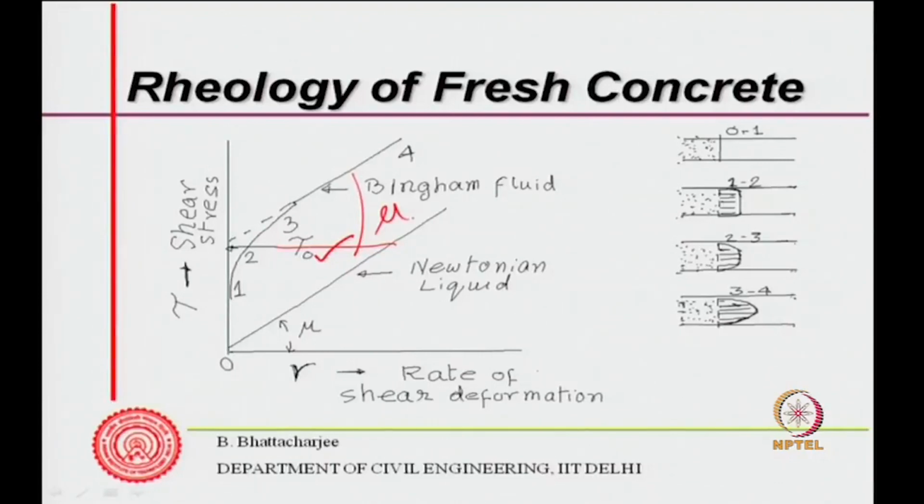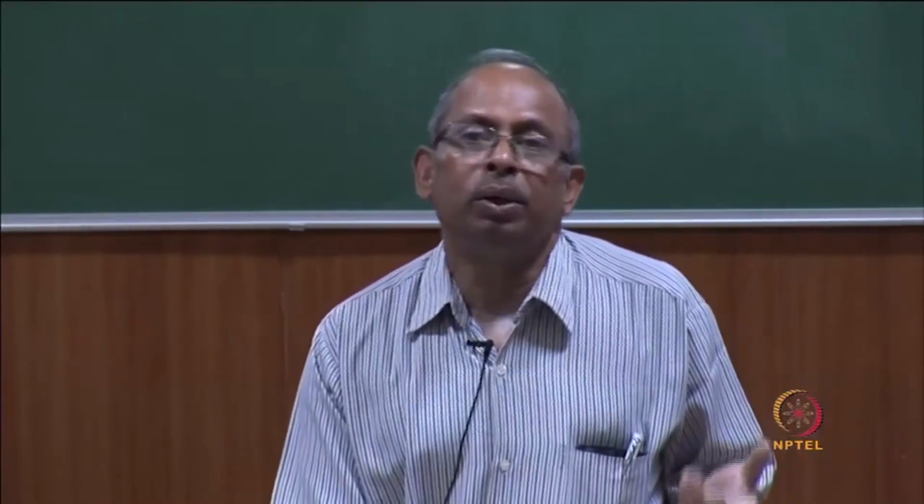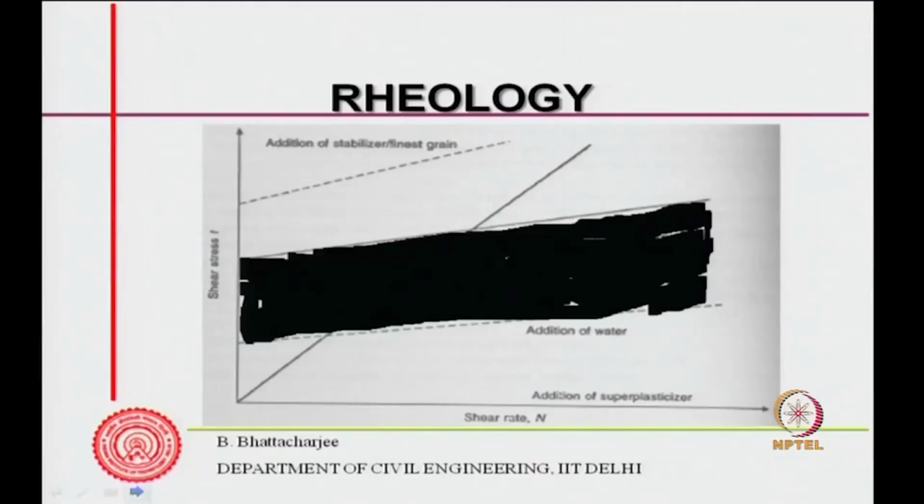So a Bingham fluid, or concrete, which is something similar, would show a yield shear stress and then some sort of plastic viscosity. These are the rheological properties of concrete. If we continue to look at it, we will find that addition of water increases the shear strain rate. Normal concrete will be somewhere here.